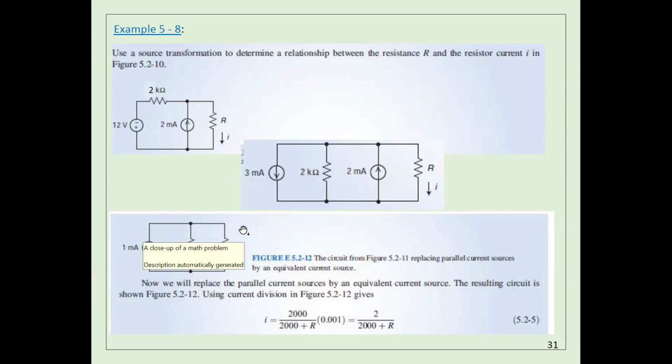Okay, guys, so let me finish with the conclusion to finish today's lecture. If you have a voltage source and you think it's going to make the analysis of the circuit easier if you convert it to a current source, yes, you can do that, as I explained, so that you can add sources together. This makes the circuit easier. Same thing, if you have a current source, you can convert it to a voltage source, okay?